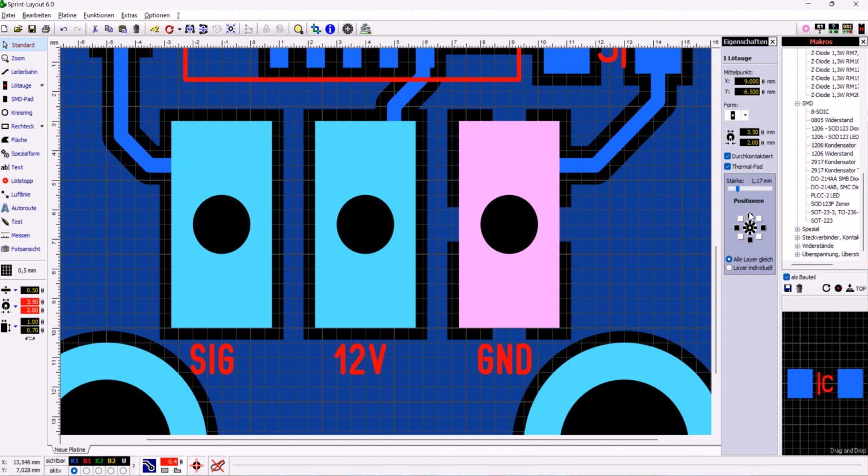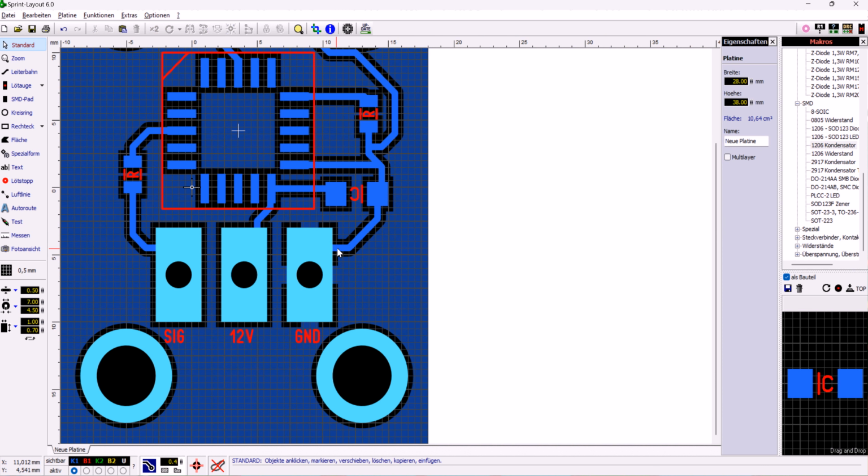And with this, I always call it a selection star. This is where you can select where the connections are going from this item to the ground plane relative to the PCB, top, bottom. So that's this connection right here. I can turn it on and off, or maybe I can say, oh, I only want the top and bottom connection, and I also can adjust how wide this very short trace would be. So that's the other way to do it.